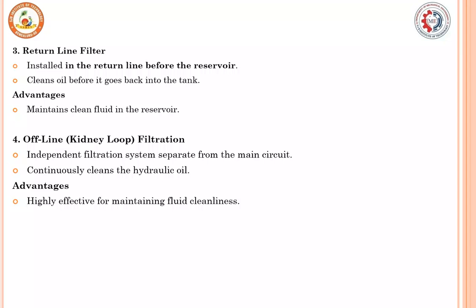Offline filtration is nothing but the kidney loop. It is an independent filtration system, separate from the main circuit. It continuously cleans the hydraulic oil. It is highly effective for maintaining fluid cleanliness.